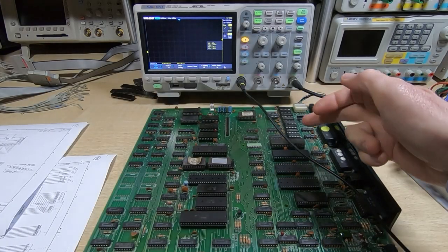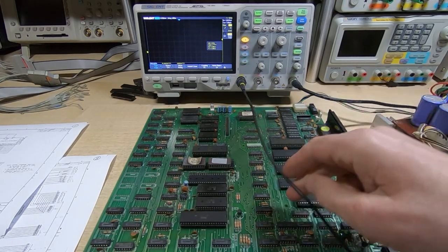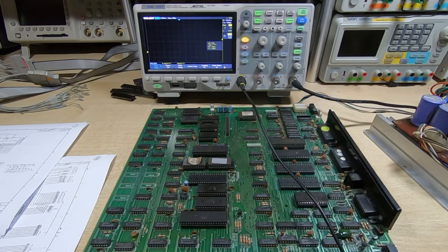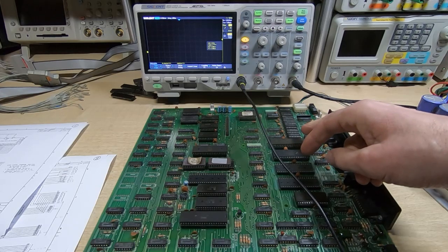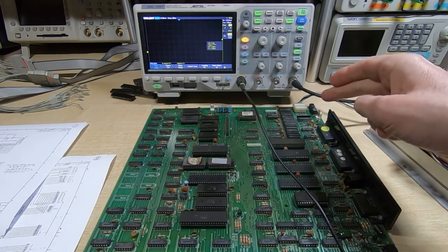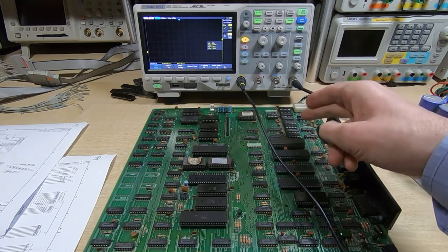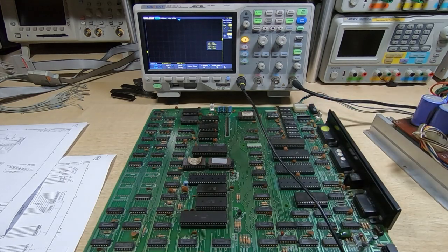As you can see, I've unplugged the clip from the logic analyzer, as we don't need it just now. We might have to put that back on if we can figure out what the memory issue is, but we know what the system's currently doing, at least the Z80 side, and we need to try and figure out why the value coming back from the DRAM is always 0. I did try it a few more times off camera, and it does return 0 every time.